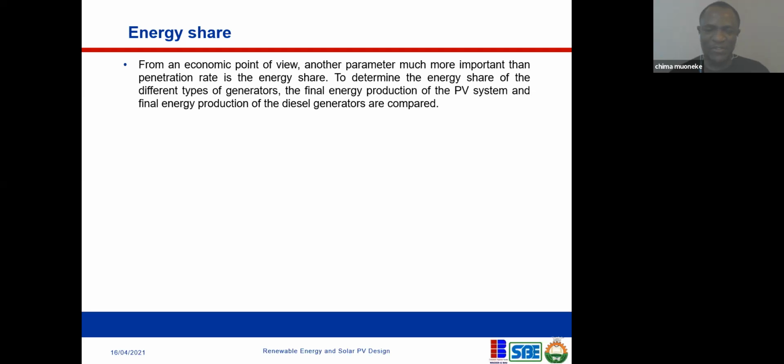When we talk about the penetration rate, we are talking about the installed capacity, the actual power generation in kilowatts, okay? But in terms of energy share, we're looking at the actual energy that was generated from the PV, and you're comparing that with the actual energy that was generated from the generator. You put the two side by side.